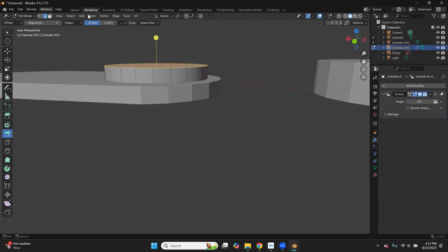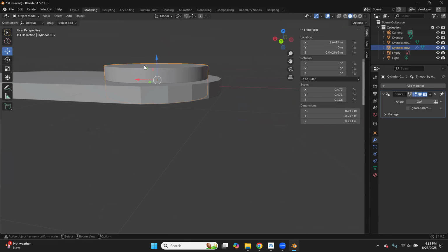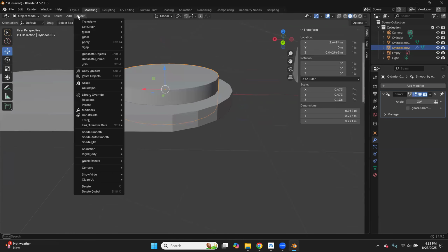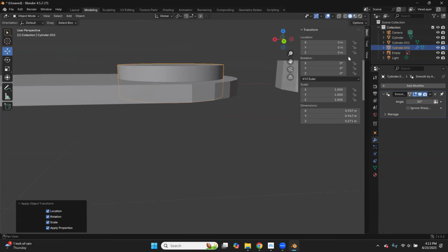And what's causing this is if I go to that, it has these transforms, like on the z-axis, and we want to clear out these transforms. So if you go to Object, Apply All Transforms, this will typically zero that out.